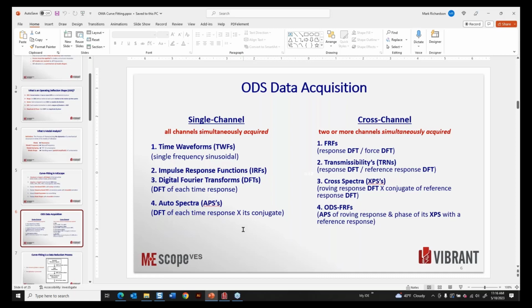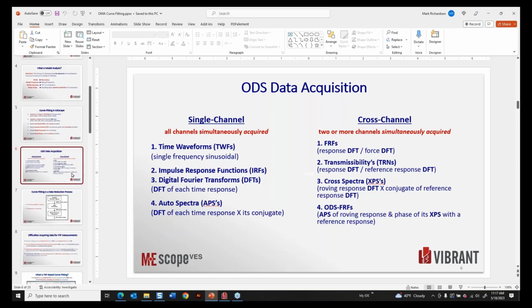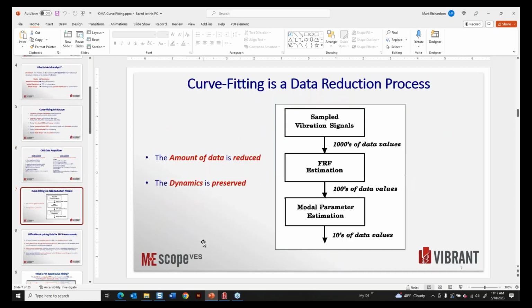So let's say we take some data off of a video, that's going to be in displacement units. And if we take data off of some accelerometers, that'll be in acceleration units. Well, we can integrate one and differentiate the other and compare answers. So it's a way of looking at data in velocity units, and many of the standards for machinery maintenance are written in velocity units. So let's move on though.